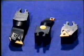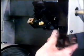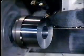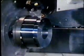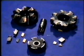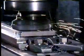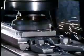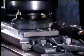The block tool has an insert already fitted and can be changed in a matter of seconds by simply slipping out the old tool and fitting in the new. The old insert can then be changed while the machine is cutting with the new tool, so a minimum amount of time is wasted. Tungsten carbide is also used for milling cutters on the same range of materials and using similar inserts. This particular example proves that the right insert has no difficulty dealing with an intermittent cut at high feed rates.